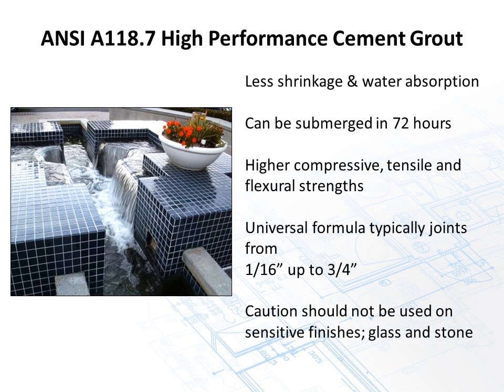Has less shrinkage, lower water absorption, can be submerged in 72 hours. Check each manufacturer to make sure of their recommendations. Higher compressive, tensile, and flexural strength. Most manufacturers today make a universal formula, so it's used for grouts from 1/16 of an inch up to 1/2 inch or 3/4 of an inch.